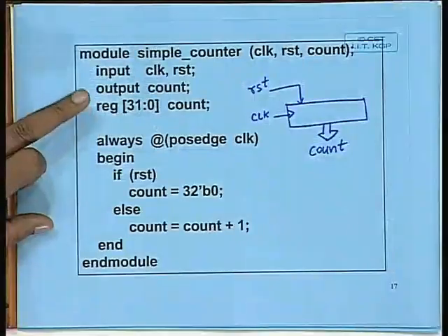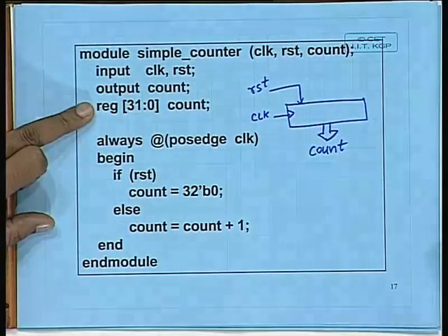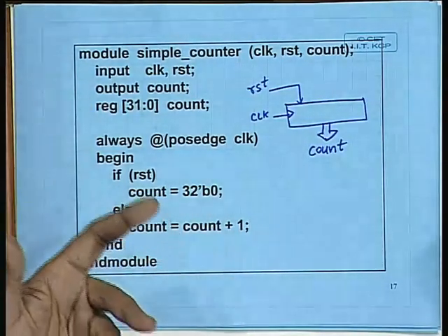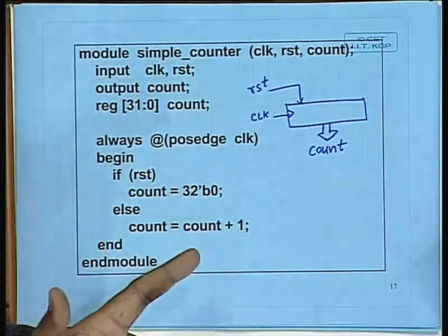Now, earlier I had mentioned that if you use integer instead of register, the exact size of the variables is not known, but the synthesizer tries to deduce the size of the value. So I have an example to show you that. If you had written integer, then what will the value of count mean in bit format? It will be in 2's complement. Whenever you are doing arithmetic, it will be 2's complement arithmetic. Well, now here it will not matter. It will be the same.